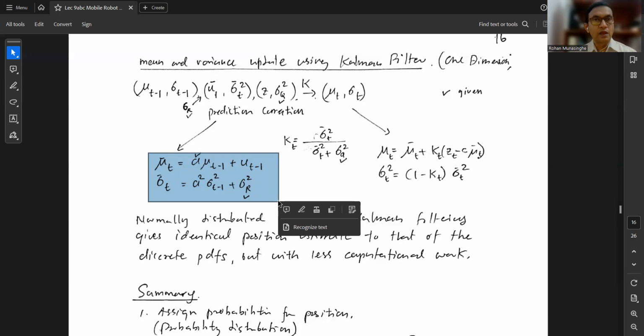Again, if you do not know it, let's say you build your robot using motors, wheels, etc., there's no data sheet to look at to figure out the motion error variance. Because it's your thing, you build it, and there are a lot of components in it. So what you want to do is drive it, very much the same way you did with the sensor. You drive for some revolutions of the wheels, figure out the distance and find out what the error is. Then immediately you know what sigma r is.